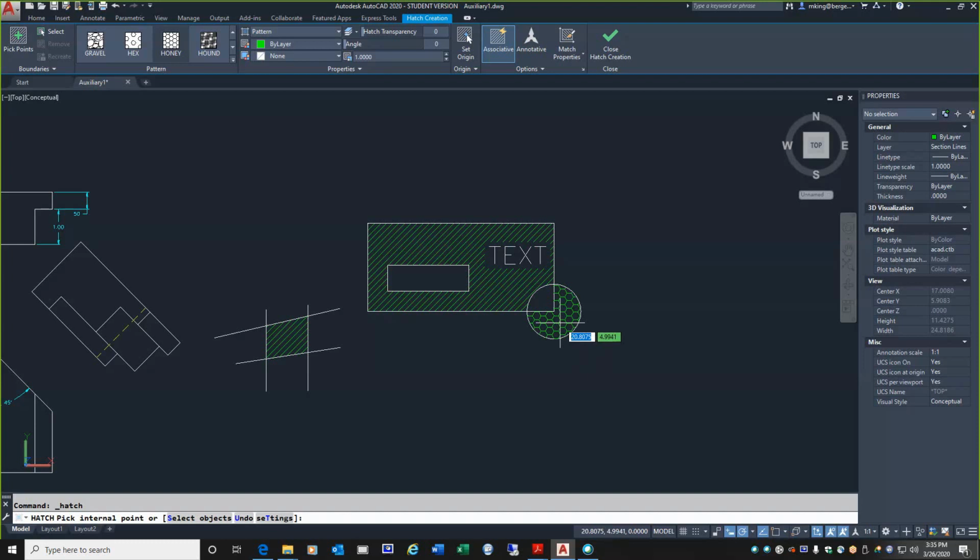So we see that I chose the honeycomb type pattern, and let's say that the pattern is too small. I want to increase the size of it. So before I click, I'm going to come up to my ribbon in my properties panel, and I've got scale, this is the angle, and I can make that more or less transparent. More on that in a couple of minutes.